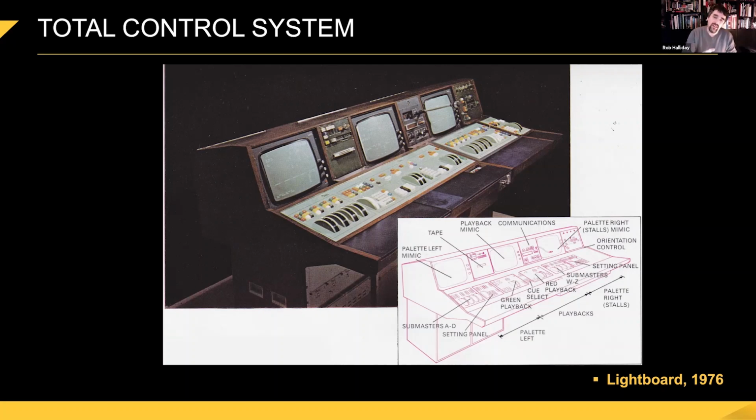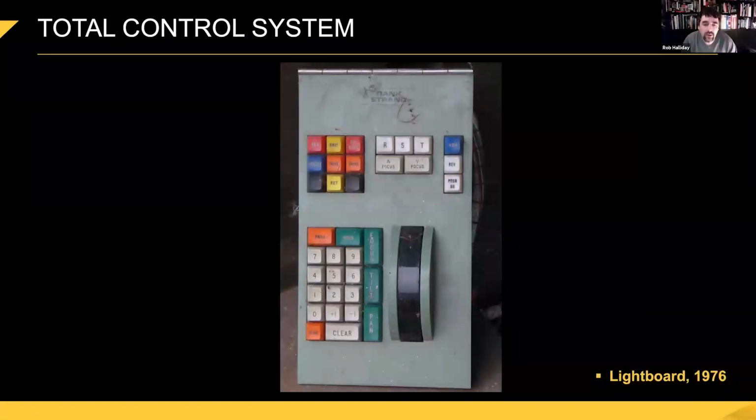And what you'll see in TCS, if you look right down the far end and you click on the little description of what everything is, a thing called orientation control. And that's the moving light control right there. And it was a panel and it had a wheel, just one, but then it had 3 buttons called pan, tilt and focus, which was all those lights could do. They could move, and then you can make the beam bigger or smaller by, like a Fresnel, moving the bulb backwards and forwards behind the reflector. So you had to choose what that wheel did. So you pan it and then you tilt it. And that sounds really awkward now, but these lights were quite slow, I'd imagine. So probably that was okay.